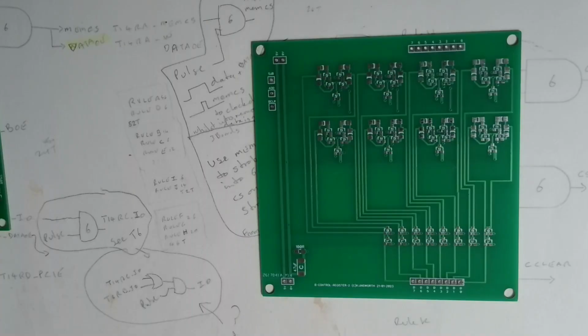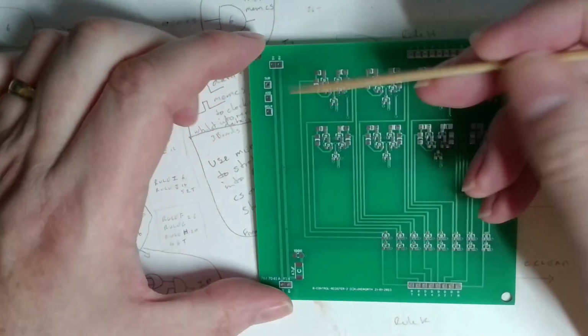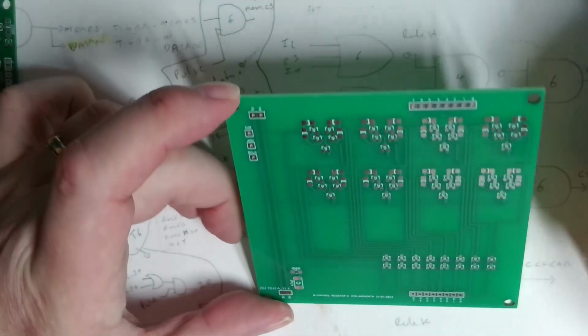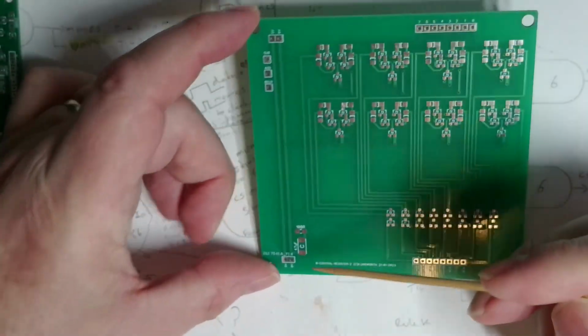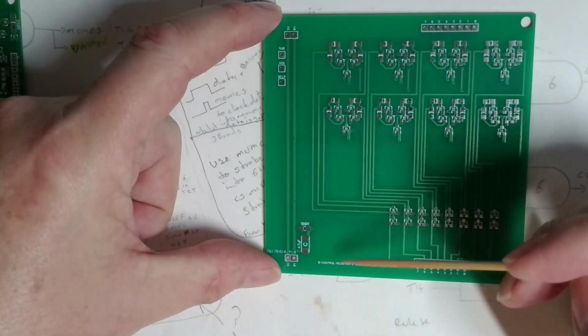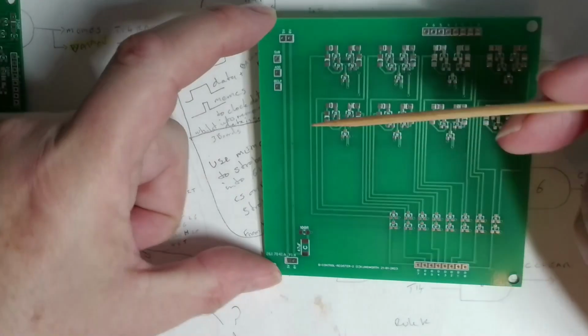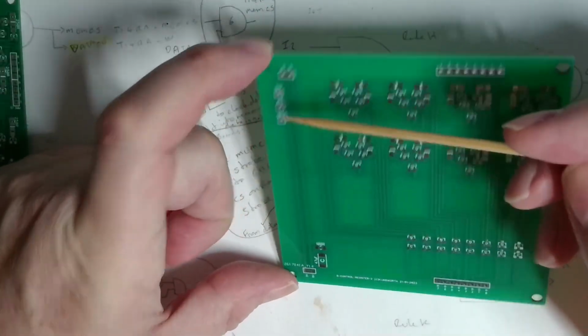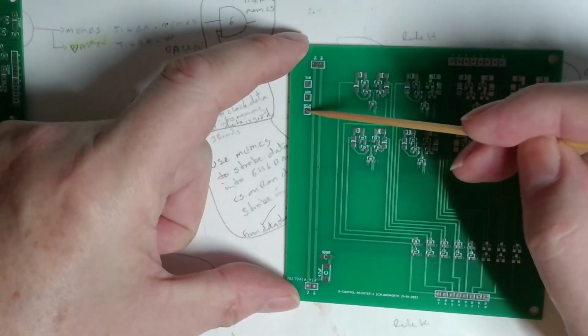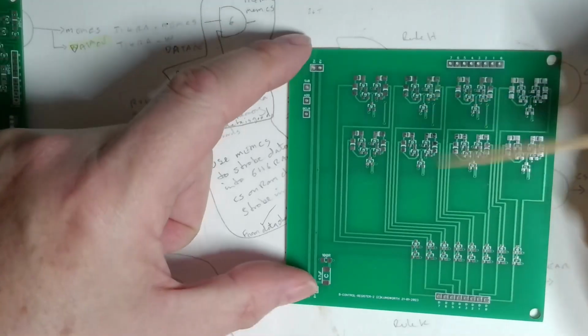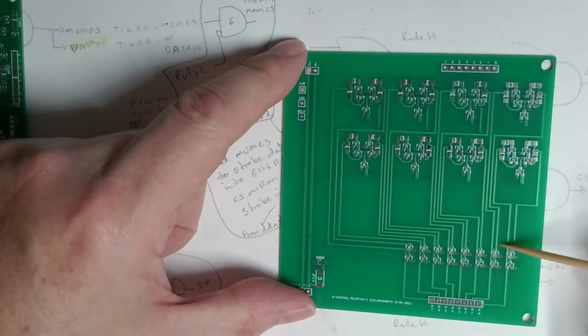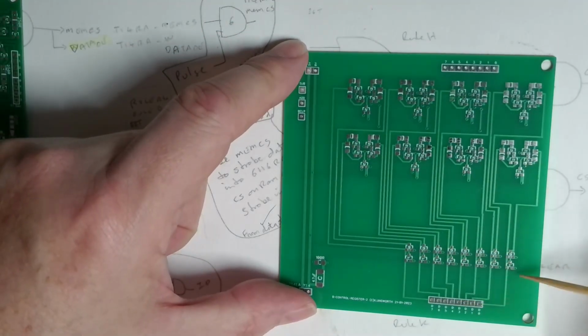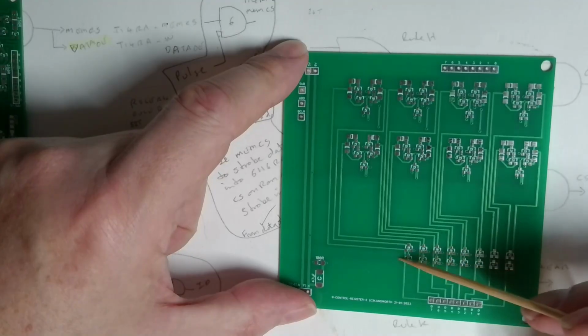Here we have the B control board. So over here, we've got the supply coming in with this time the decoupling capacitor at the bottom for some reason, and the Magic Blue smoke resistor. Over here we've got the sub, add and B clear signals. So these transistors down here, if the B register comes in here, these are the inverters.